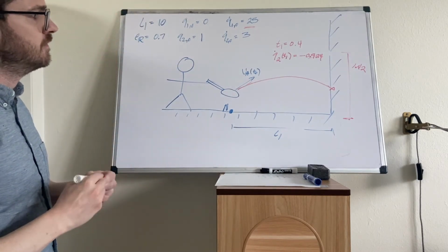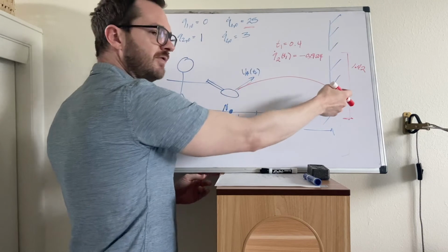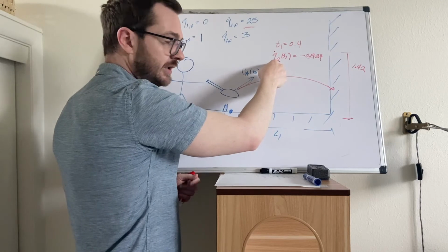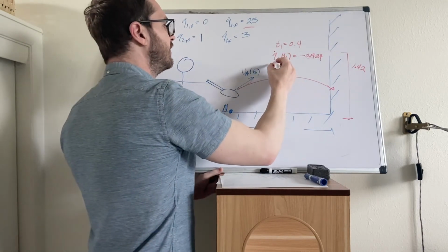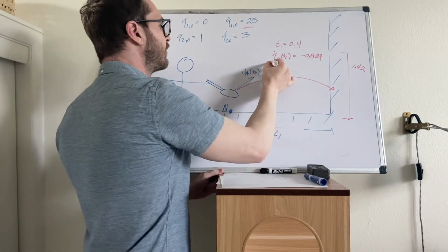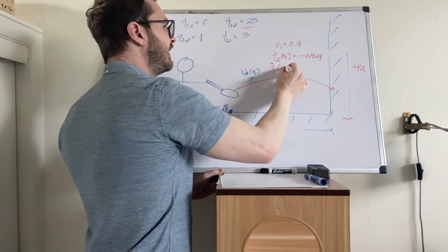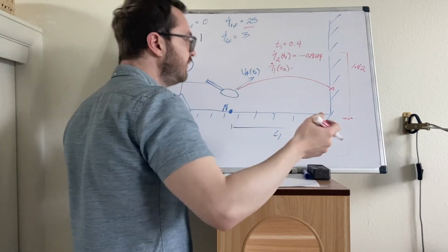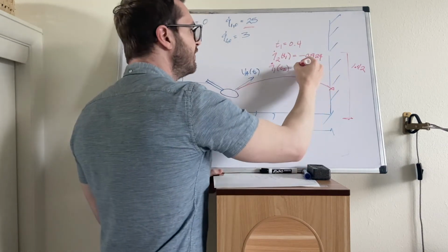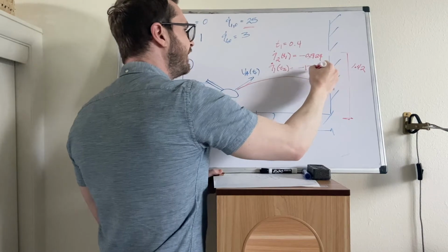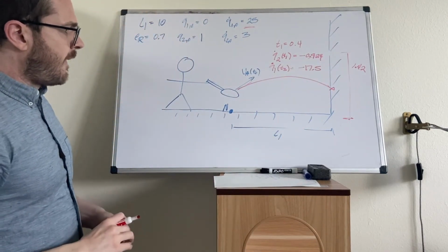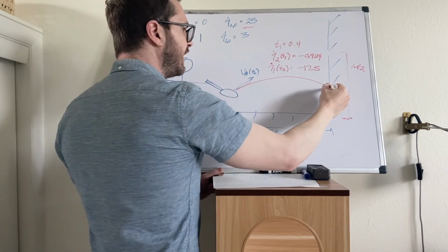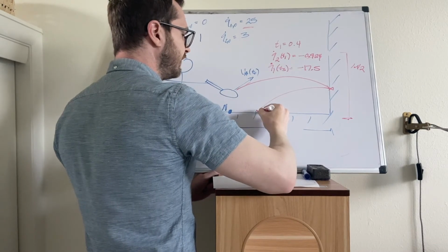All right. Next, so we performed this impact analysis. What's going to change? Well, the vertical velocity is going to remain unchanged, and the x velocity is what is going to change. So in this first impact analysis, we're going to solve for Q1 dot at time number 3. Time 3 is just as the ball is separating, so it goes into the impact at 25. It is leaving the impact at negative 17.5 in the x direction. Okay, we have these. We put these back into those same ballistic equations and we solve for time. We find that the ball is going to come back. It's going to strike the ground.